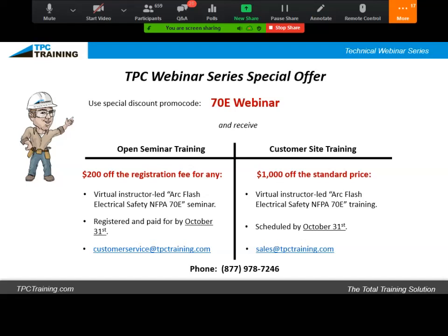Here's a question for you, Bob. One person finds that many of their electricians have not been trained on 70E since about 2008. Is that a problem? Yes. In the 2012 version of 70E, there was a proposal, accepted by the technical committee, that all electrical workers, qualified electrical workers, and anybody that might be exposed to a hazard, that would be the unqualified people also, have to have updated training every 3 years.